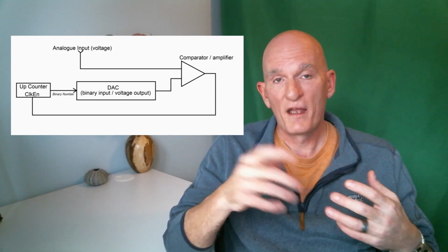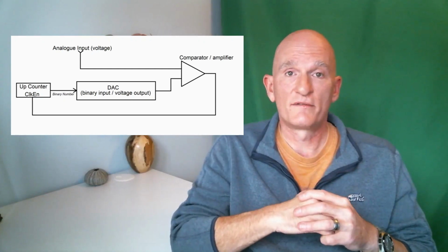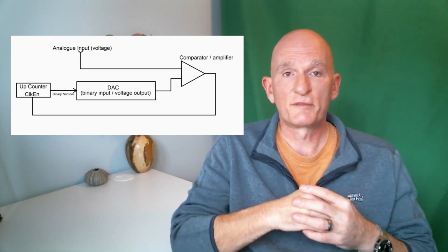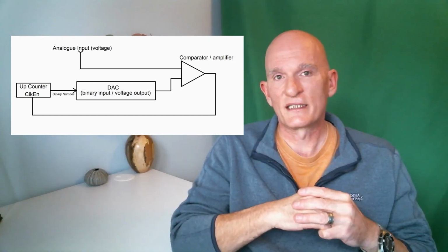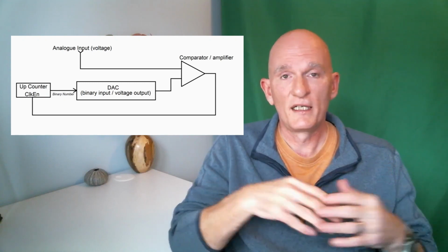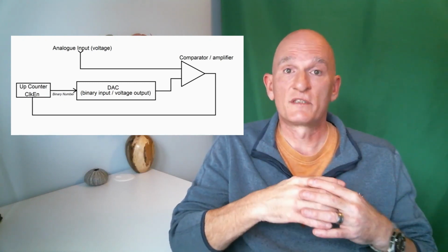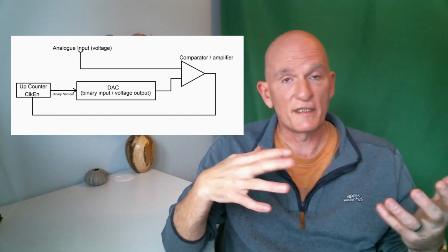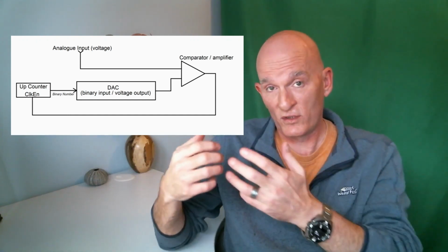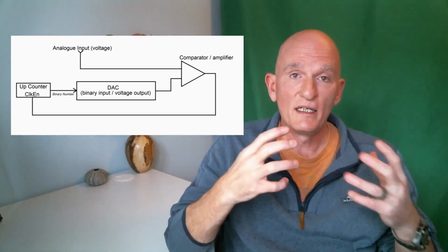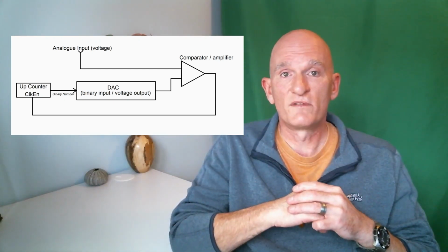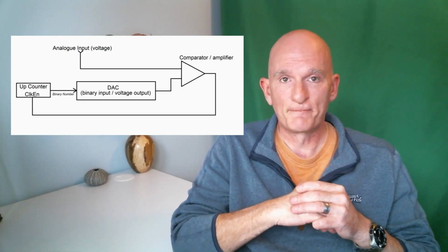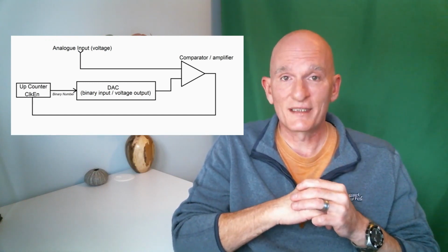Now typically within an analog to digital conversion, you'd do this conversion several times because there'll be noise on the signals and things like that, and you'll take the average of the result. How many samples you take to get that average will depend on how fast your output is expected to move and how much noise you're aware is on that signal. So you can tune analog to digital conversion depending on the specific signals that you're trying to measure. But that is how analog to digital works.